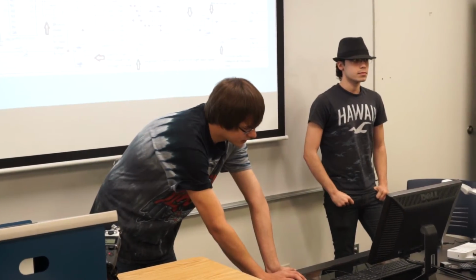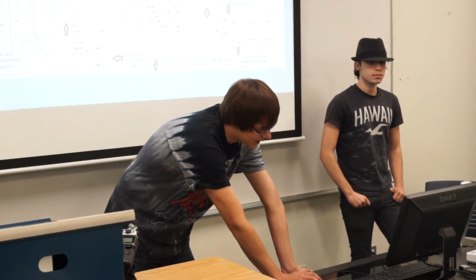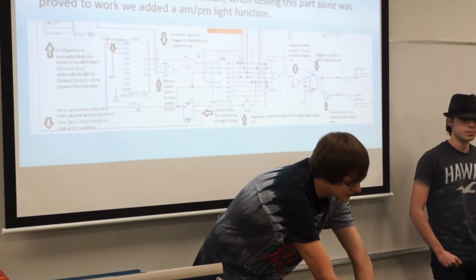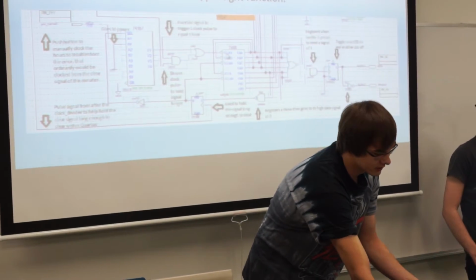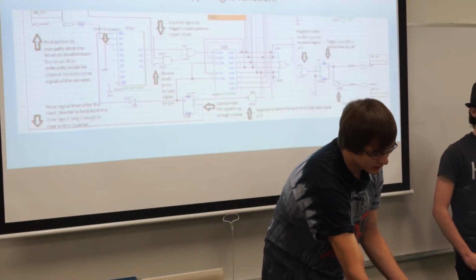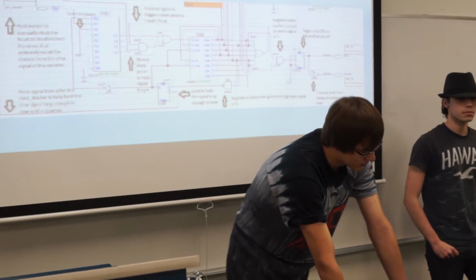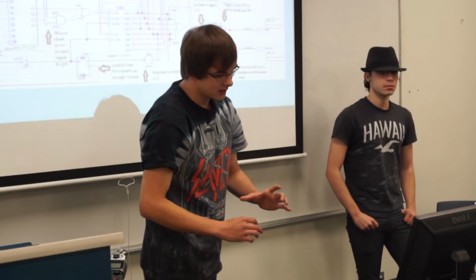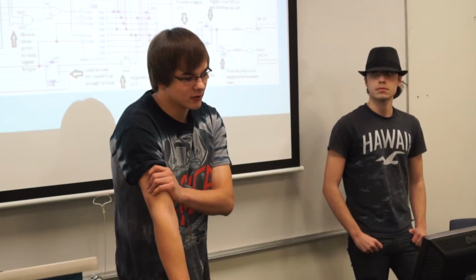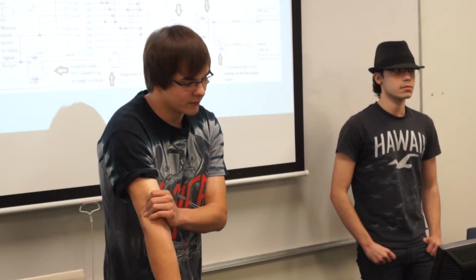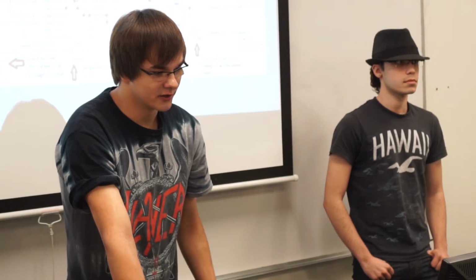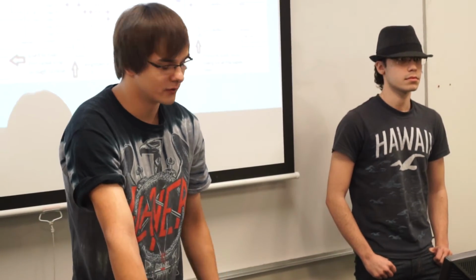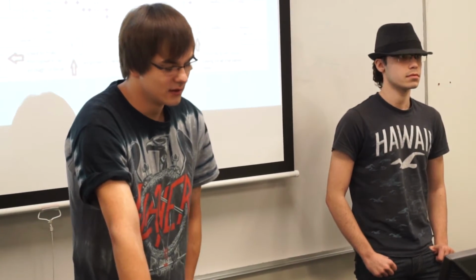When we had a push button here for our 1 o'clock one for the hours, because you don't want to wait 60 minutes just to see if your thing works, it worked fine with the push button. We could push it and it cycled over, then went to 1. But for some reason, when we tried to hook it to the minute output that would lead into the hours, it did all sorts of funky things, counting to 99 or clearing to 2, for no apparent reason.